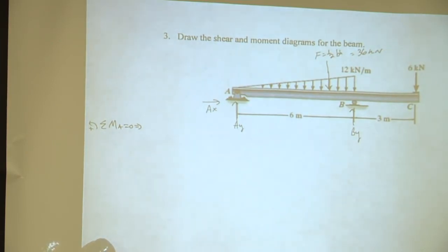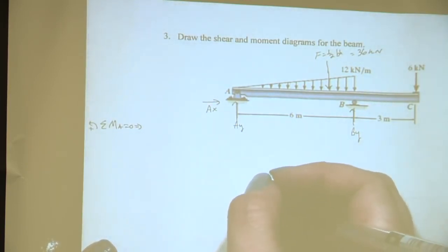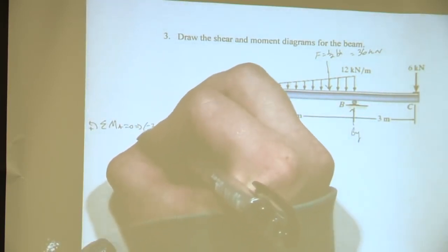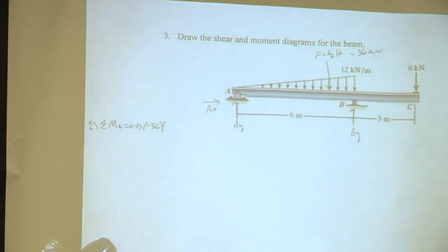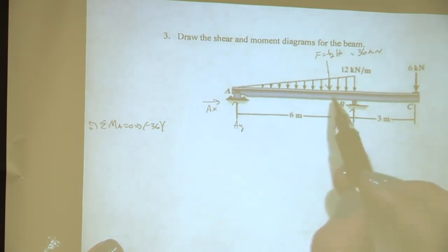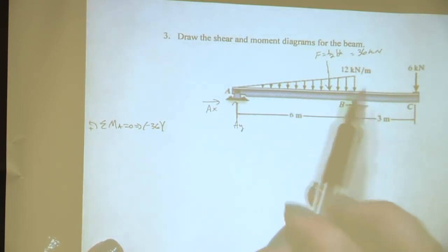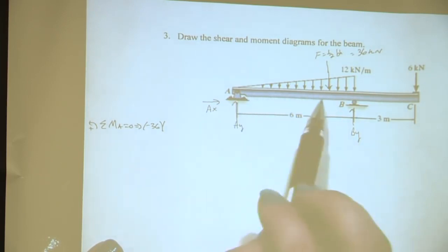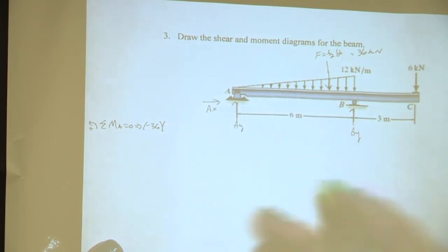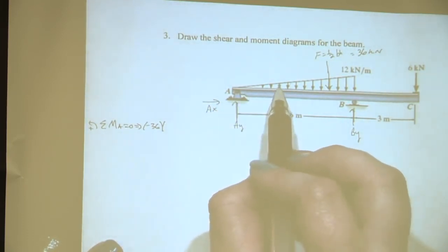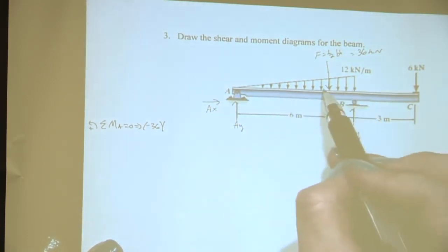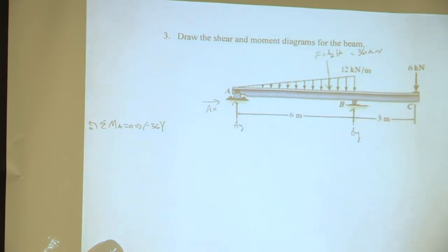Okay. So which one do you want to start with first? The triangular distributed load force? Yeah. Okay. So should it be positive or negative? And then what is its perpendicular distance away from A? It's 2/3 from the one. Okay, awesome. So this is located 2/3 from this distance. So if you're ever unsure if it's 2/3 or 1/3, look at it like this. If it was 1/3 away from A, does it make sense for the centroid to be right there? Sure. Does it make more sense for it to be over here? Yeah. So that's one way to do it.